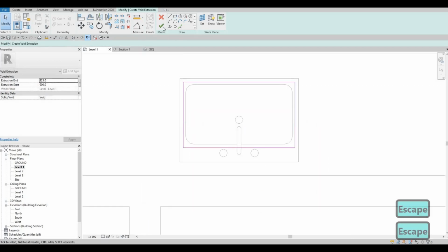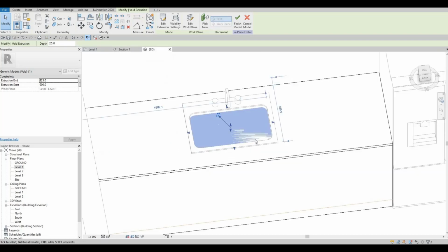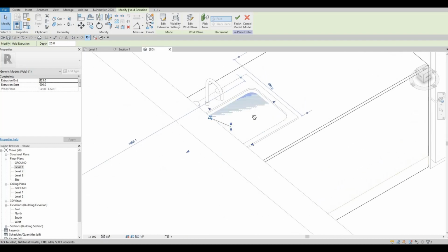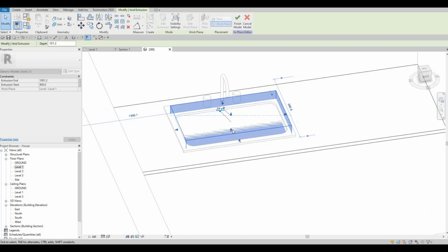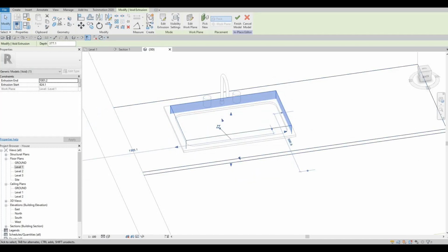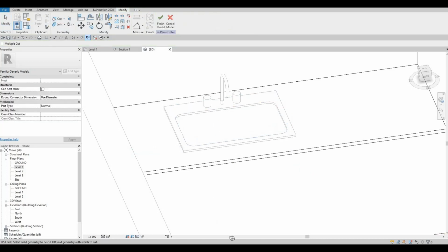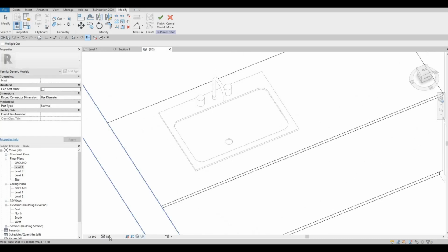so that it's not blinking, because if anything is exactly overlapping each other, it's going to keep on blinking when you put it in Twinmotion, and that's the effect of overlapping. As you can see here, that's the blinking that I'm referring to, because it's just overlapping each other. Now I'm just pulling this out, and then I'm going to click on cut geometry, and then as you can see the hole is now there.